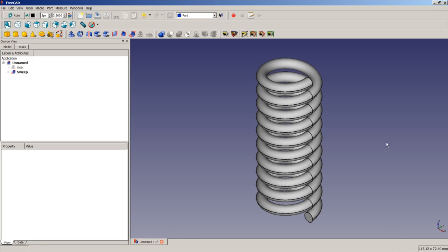Technically speaking, we want to make sure that the compression spring only moves along its main axis and does not move in any other direction. So therefore, we will insert two cubes and make a Boolean cut with the compression spring modeled here to show this also in our 3D model.